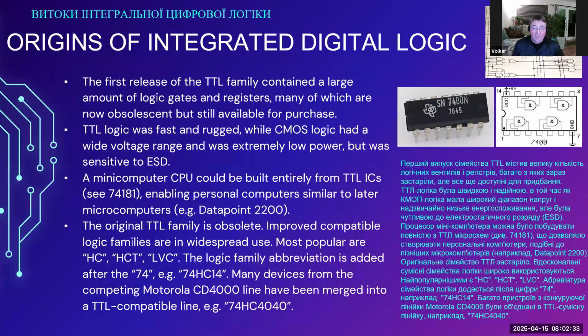And you can buy the same chip in a newer family, in an HCT family, and the chip will still have the same pinout, even though it might be in a much smaller package. It might be in a SOIC package or in an SSOP package or in a DSSOP package. It will still have the same pinout. So that was pioneered in the 1960s, and we are still living with that today, basically. You can still go to the store and buy a follow-on, like a newer chip with better technology. It has the same pin layout.